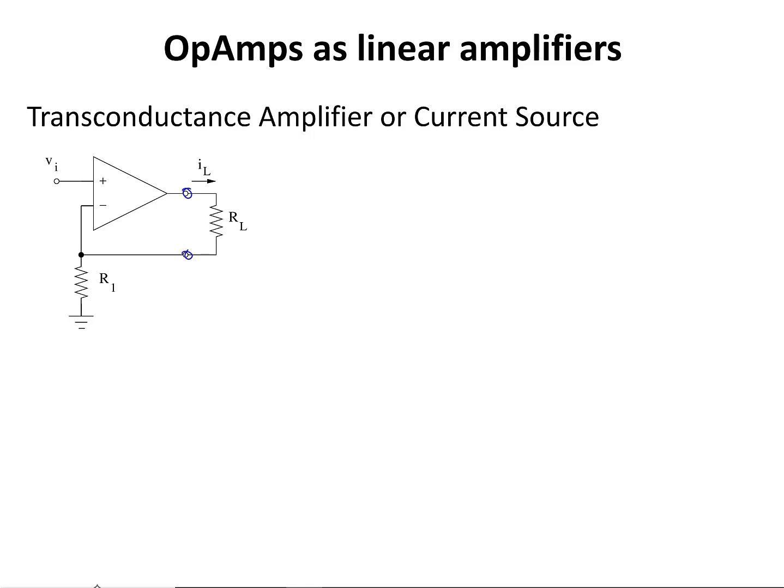So again, I'm going to use the first and second golden rules of op-amps. IN is almost equal to IP, that is equal to 0. I'm going to assume an ideal op-amp, also because there's negative feedback. There's this negative feedback network, and the output of the op-amp is connected through a resistive network to the inverting terminal of the op-amp. From there, Vn is going to be almost equal to Vp.